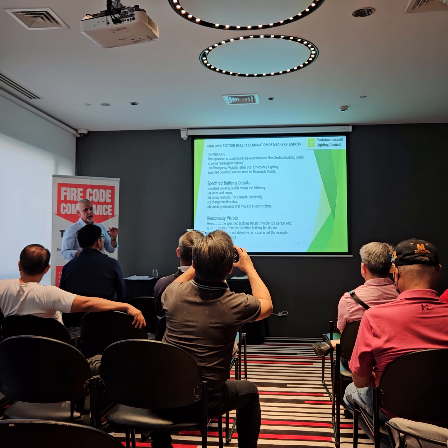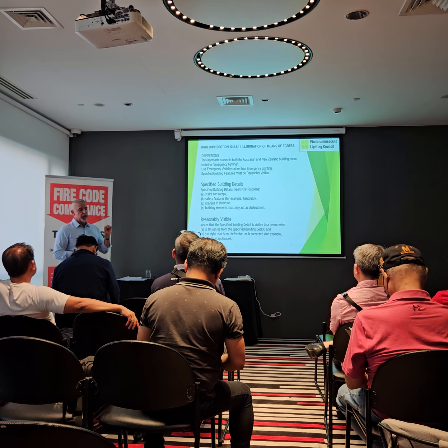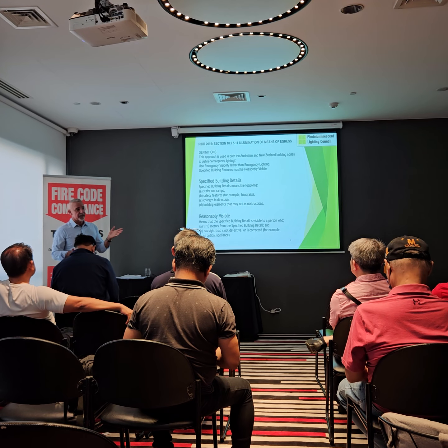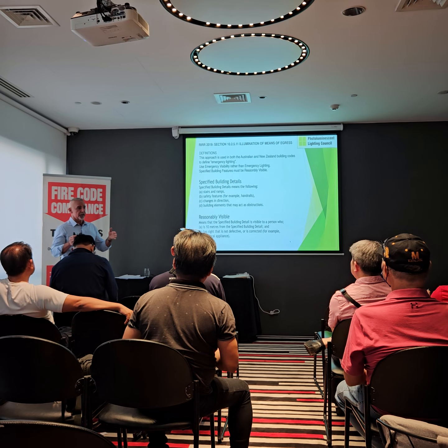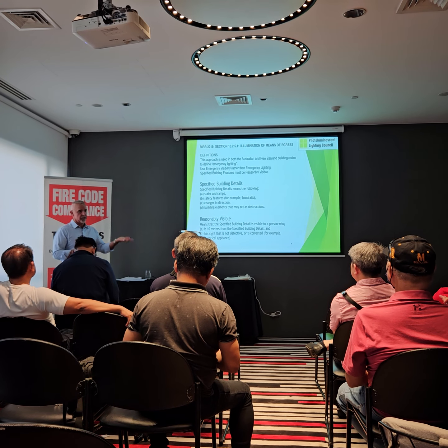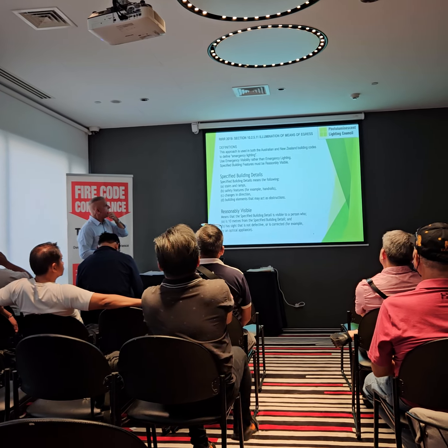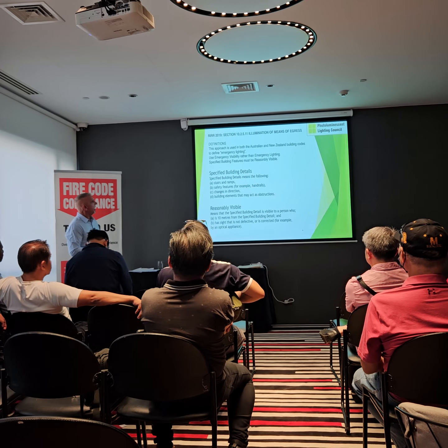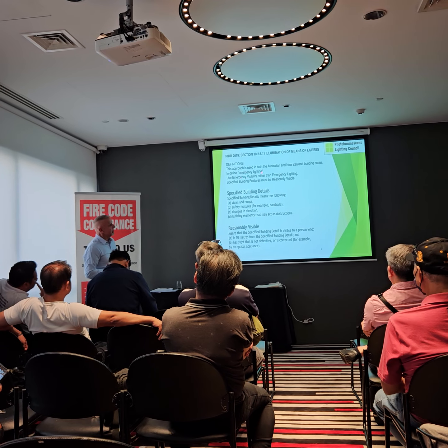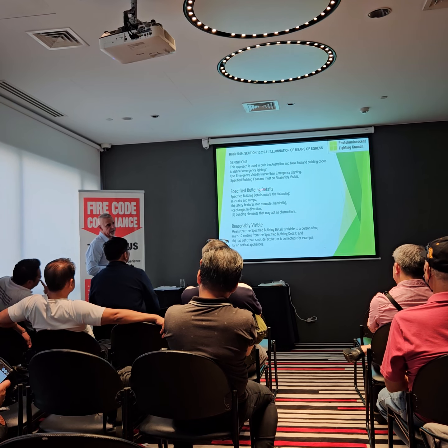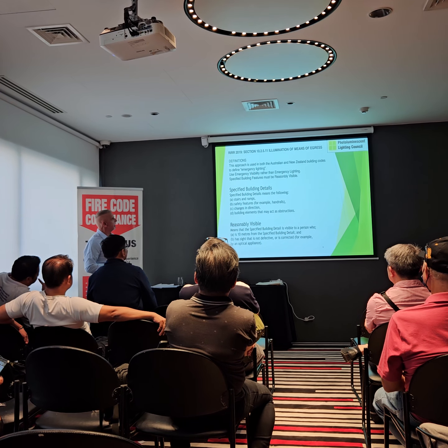So I mentioned in Australia and New Zealand, you can actually replace electrical emergency lighting fully with the photoluminescent system. So build a new building, photoluminescent, yeah. So we've taken some definitions that are used there, and basically even the word emergency lighting has been taken out of the building codes in Australia and New Zealand, and they talk about emergency visibility.